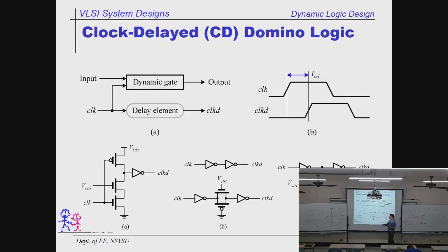That's methodology number 1. The second one is that if this is not good enough, you can do this way. This is a resistor. This is a transmission gate over here. So this is on, this is off. Then you can create a delay over here. Okay, this is number 2. Use the RC delay. And the last one is personal, my favorite.